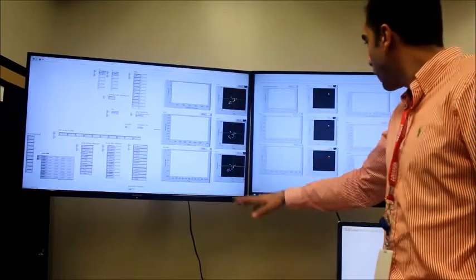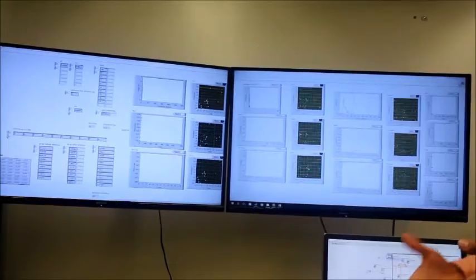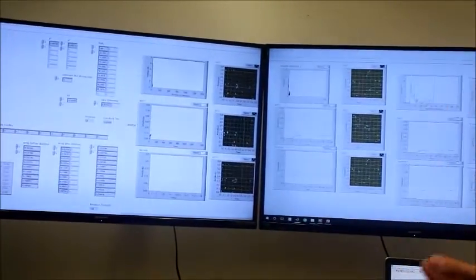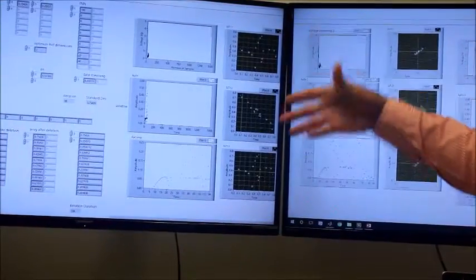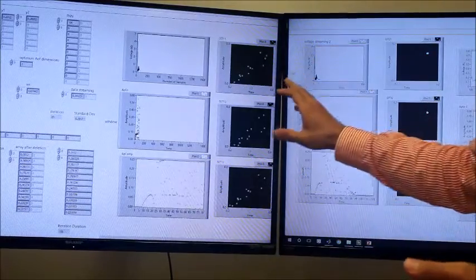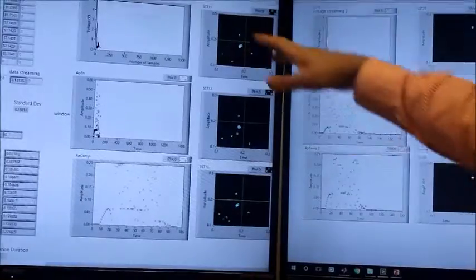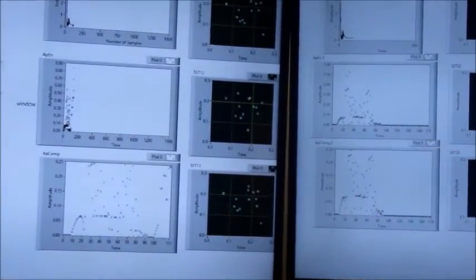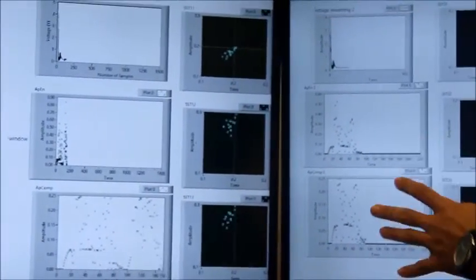These 3 figures over here show the phase space, which is the visualization of the dynamical behavior of the system, because in the real-time target it's impossible to show the system in 3-dimensional phase space. I am using 3 two-dimensional phase spaces, so XY, XZ, and YZ. Like I said, I want to mention again that this part is for the load switching, this part for the high impedance fault, and this part for the islanding condition.